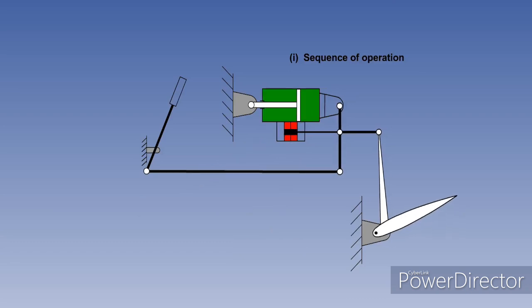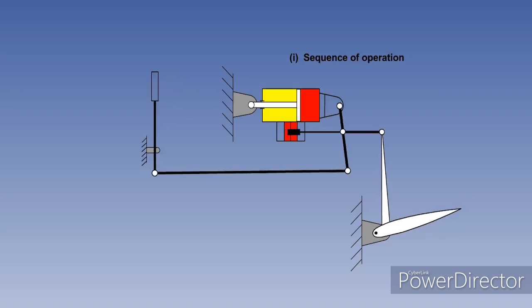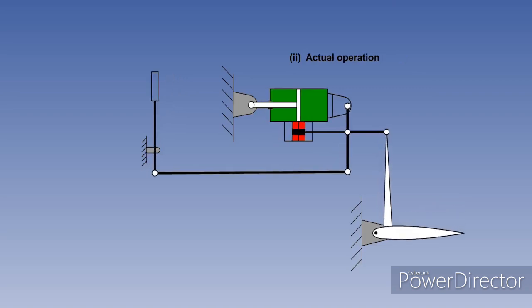The reason for this design arrangement is to make sure that the control surface is moved to the angle and at the rate required by the pilot. This is called follow-up. The force from the hydraulic system moves the body of the PFCU and the control surface until the input from the servo valve is cancelled by the motion of the PFCU body. A hydraulic lock now exists.